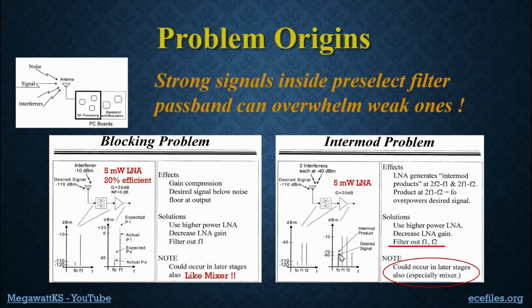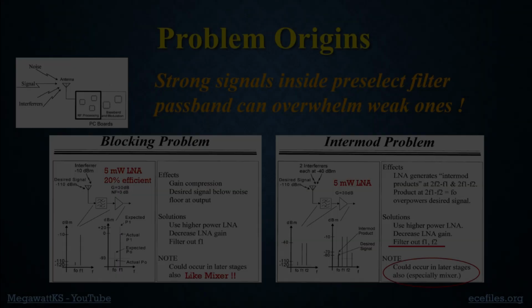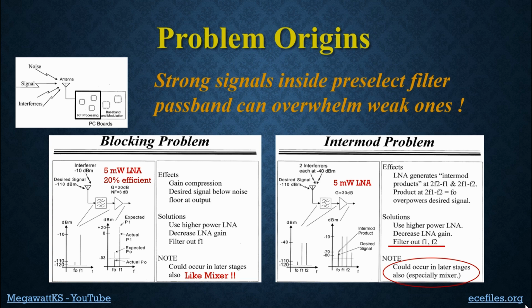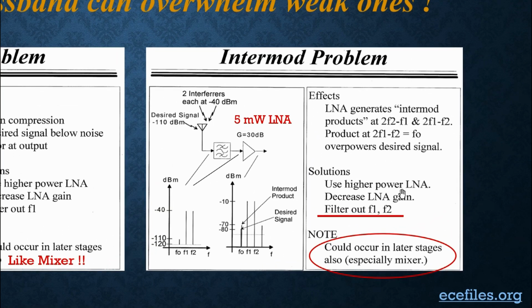But the desired signal we will not hear because it's weaker. So what can we do? Well, same as before. You can use a higher power low noise amplifier, burn more power, but we can't because we're trying to design low power receivers.